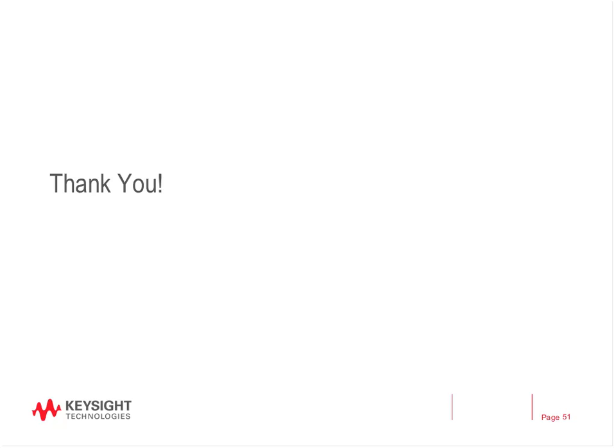Okay, thanks, Pat. So here's another question. Why do the second and third order products cause more problems as compared to other order? That usually has to do with their magnitude and the fact that typically second and third order mixing products have a tendency to mix in band with your actual signal of interest. So together with their magnitude and their tendency to mix in channel, those always end up being the biggest ones you want to chase first.